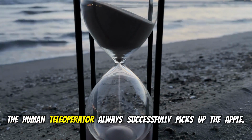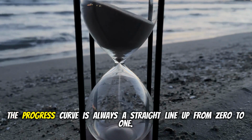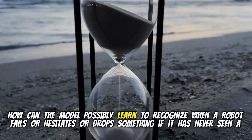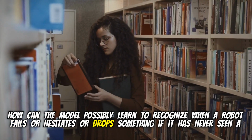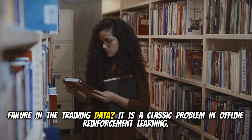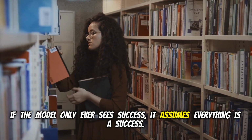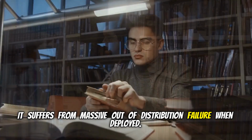Yes. The human teleoperator always successfully picks up the apple. The progress curve is always a straight line up from 0 to 1. How can the model possibly learn to recognize when a robot fails or hesitates or drops something if it has never seen a failure in the training data? It is a classic problem in offline reinforcement learning. Yep. If the model only ever sees success, it assumes everything is a success. It suffers from massive out-of-distribution failure when deployed.